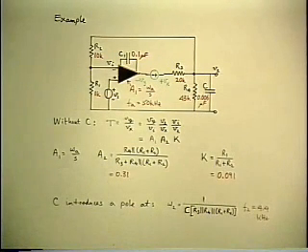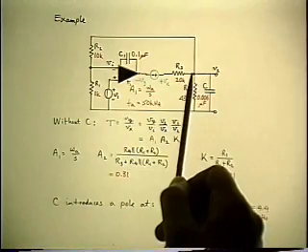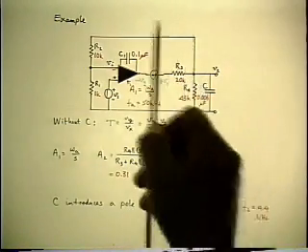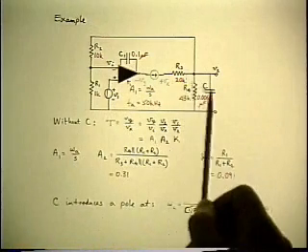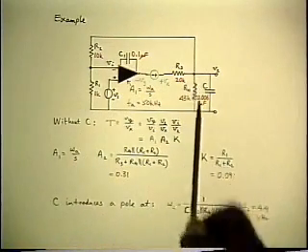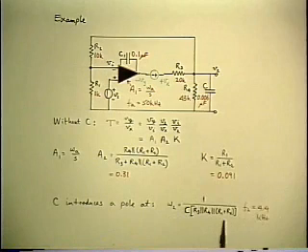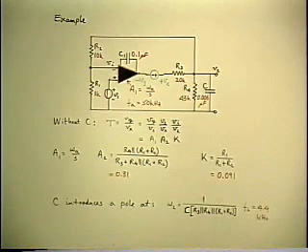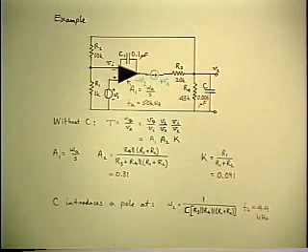But of course that could have been seen to begin with also, because this capacitor is right across a node through which the signal passes in determining the loop gain. So at infinite frequency, the capacitor will short the loop, and the loop gain will be 0 at infinite frequency for that reason. So the capacitor produces a pole, but it will not produce a corresponding 0, which is consistent with the detailed result that when you solve for Rn, the answer is 0.